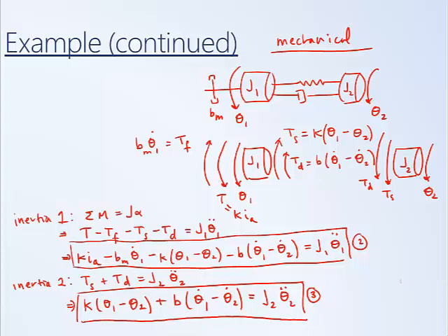If you think back, one quick and dirty way to give some confidence that we've oriented our torques in the right direction is to look at the signs on our variables. In these sorts of systems, all of the theta 1 terms should have the same sign, and all of the theta 2 terms should have the same sign. So here, if I distribute this negative K, this becomes positive.